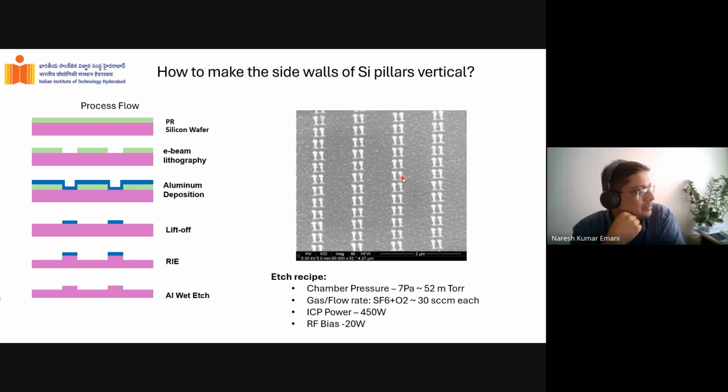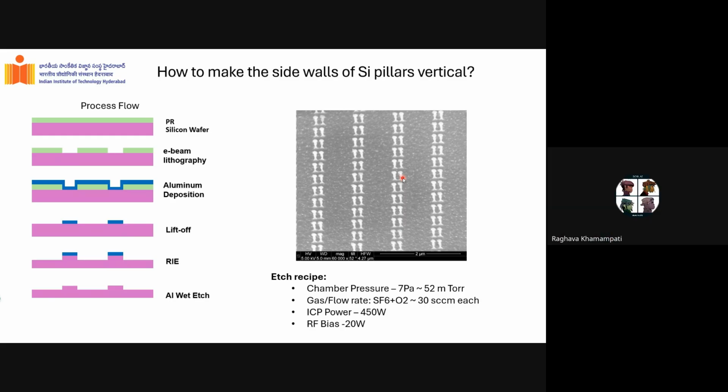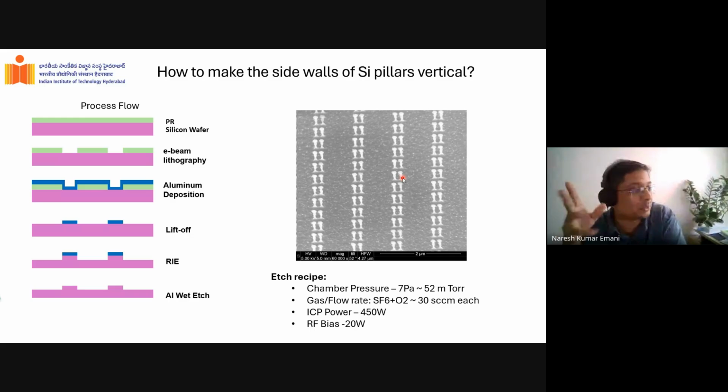What is wrong here? Small pillars. Yes, of course, they are small pillars. Yeah, why? What is wrong? Etching looks like it was isotropic. So because of that, what should I do, Rahul, for that? There is like a bulkhead. Yeah, bulkhead. So in the top, there is something that is protecting, but underneath there is more isotropic etching. That's why you see that these things are almost standing on a very thin waist region. There is some undercut, essentially.